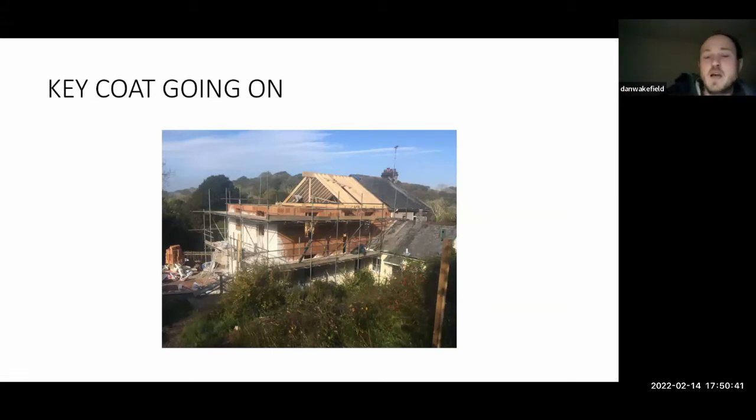Sorry, don't mind if they get wet, you know, that massively affects how well the render sets. So one of the things we struggled with, when doing it slightly later than would have been ideal, is that it took quite a long time for the blocks to dry out, and then that affected our plaster. The knock-on effect is that the plaster's taken much longer, which has meant we've not been able to tape to the plaster.